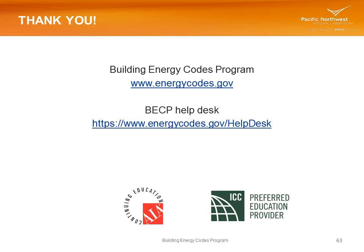I think that you get the savings, and you could combine a direct DOAS, or dedicated outdoor air system, with a VAV system and then shut off the heating and cooling completely from the VAV system because your ventilation is in a separate system. That's probably where you would get similar savings to a radiant system, but they can both work.